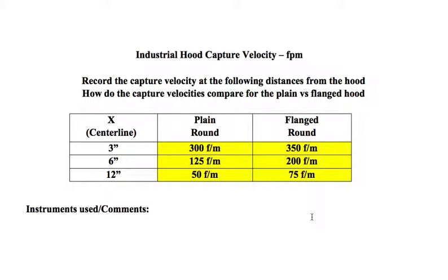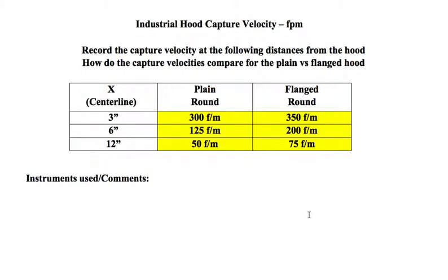The next part is a part where we looked at the performance difference in a round hood where air could get sucked around easily around the side. So you lose some of the air that you intend to use to do your work of capturing the contaminant in front of the hood opening, right? You lose some of that.